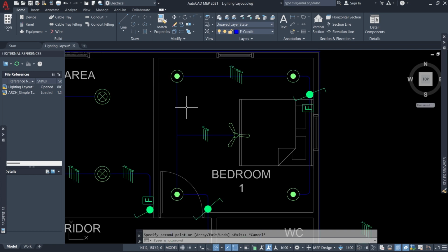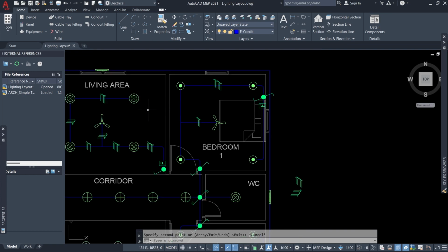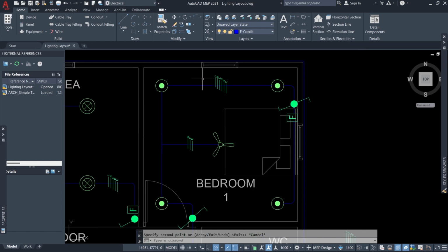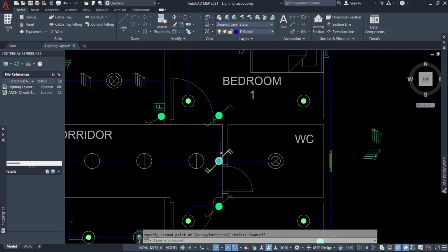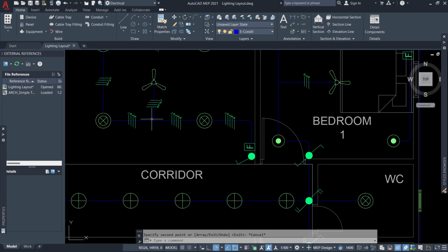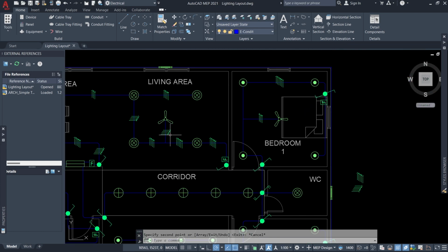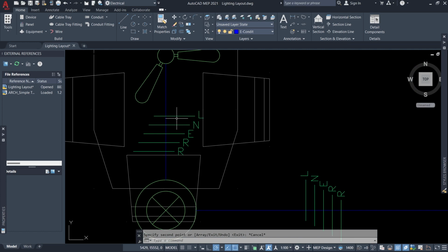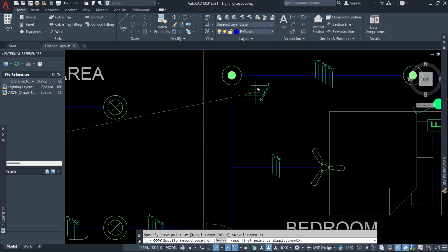And now we are still going to have our live cable run through the system because the live power is coming from this point. Okay, so we are still going to have our live, neutral, earth. How many returns? I think 2, and then a control.